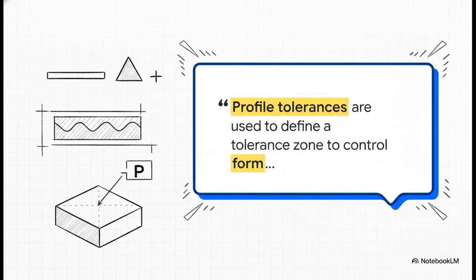Boom. Now, if you're wondering why engineers absolutely love this tool, it's because it saves you from handing a machinist a ridiculously cluttered drawing that looks like a spider web of dimensions. Profile can literally replace flatness, angularity, and position, all on one single callout.